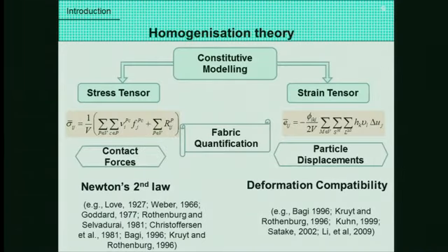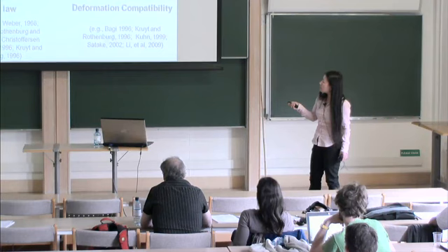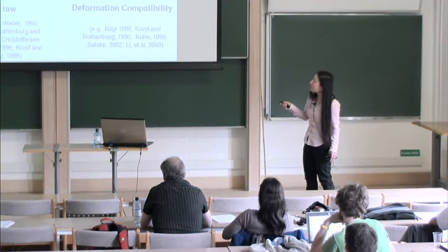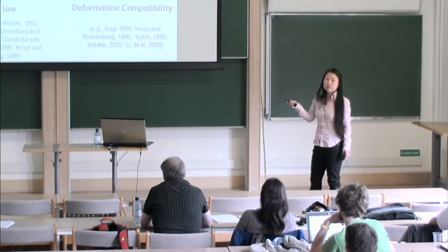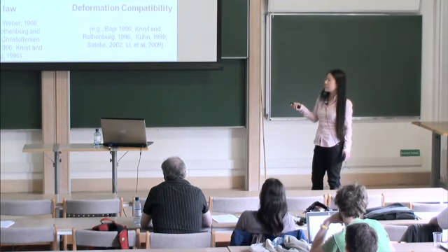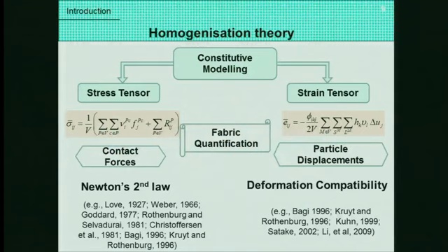So there are some achievements on the theoretical side. These two equations may be a little bit complicated, but actually it's quite a rigorous set established. This equation gives a relationship of the stress tensor to the particle contact forces and the local contact vector, the local geometries. The setup of this equation is only based on Newton's second law. And as long as we have a simple element which can be considered uniform, that's valid.